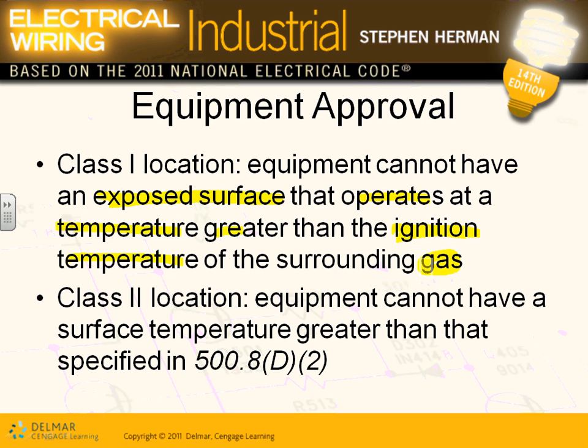It goes without discussion, temperature is a big deal when it comes to hazardous locations. T, you're going to hear a lot about T. In a Class 1 location, remember, the exposed outside surface temperature of the equipment cannot exceed the ignition temperature.